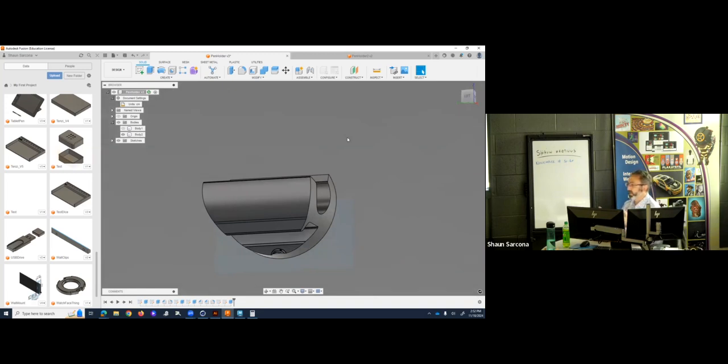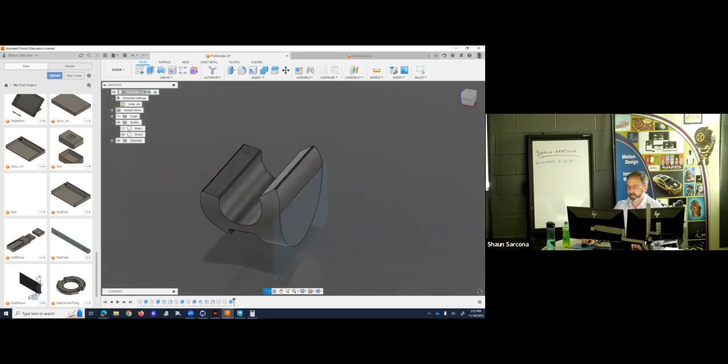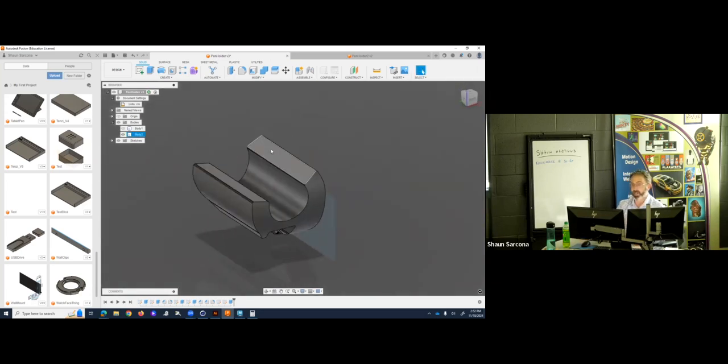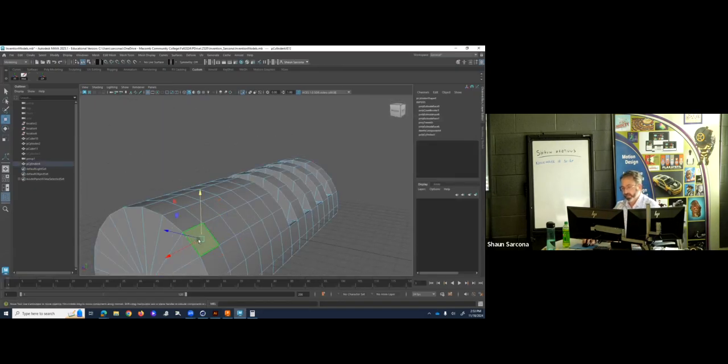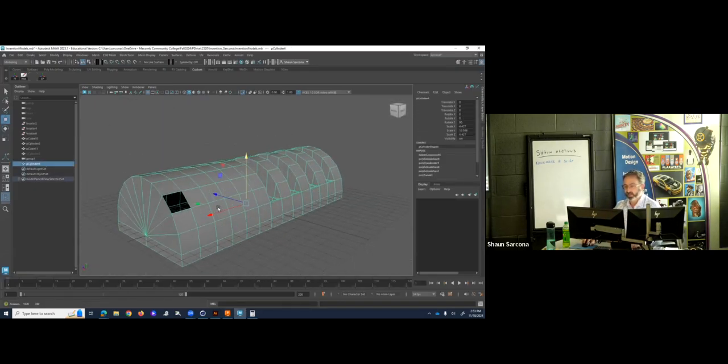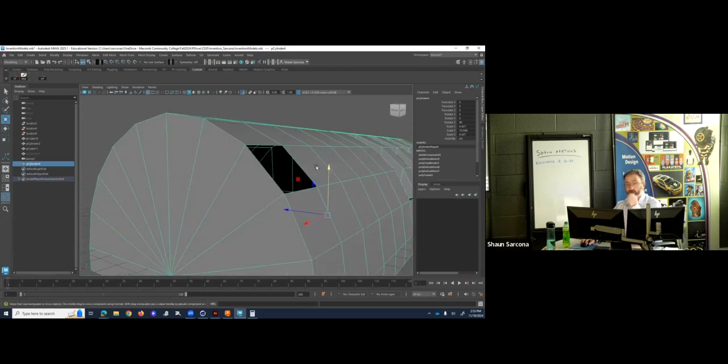If you want to use Maya, Cinema, Fusion, some other tool, feel free to explore any of those. The end result is going to be an STL. It has to be watertight. That means that there's no openings. If there's even a single opening on this, like this face is empty here, it won't print because it'll think it's paper thin and it just won't know what to do.